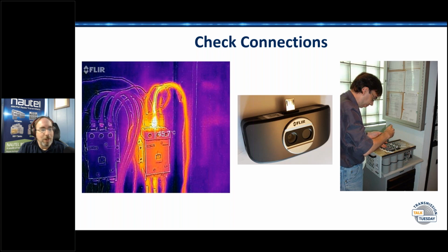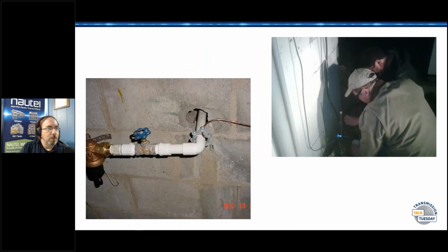I joke up here, I grew up on a farm, and our biggest crop was rocks. But so, inspecting your ground system, little details. If you're taking over a new site, go through and make sure that the ground is actually ground. Everybody's seen this picture at least once. I will stop using it the day after I retire. But somebody told an owner-engineer that a cold water pipe was a good ground, so he found himself a cold water pipe, and that's where he connected the ground for his transmitter.